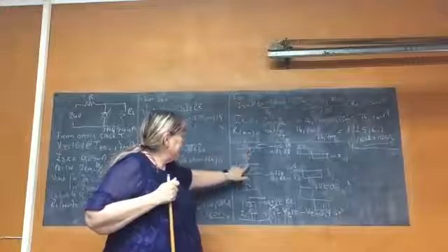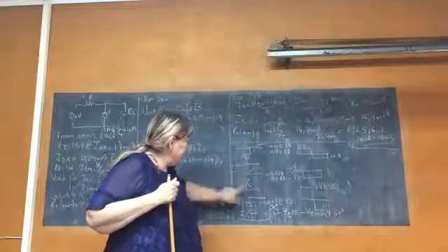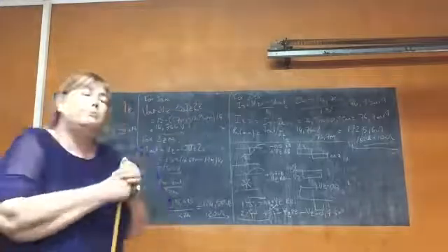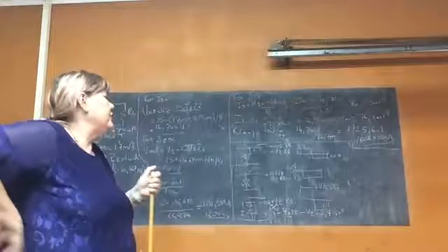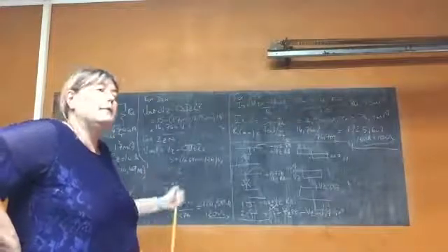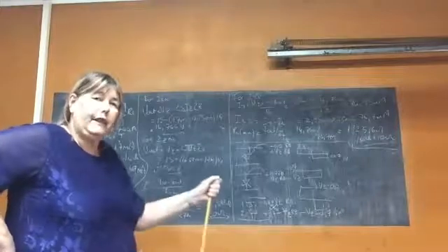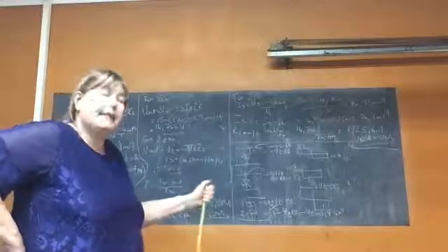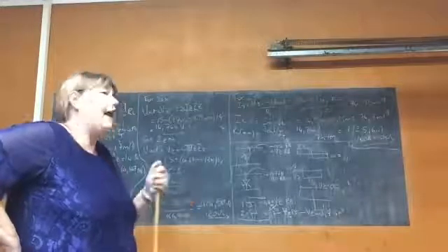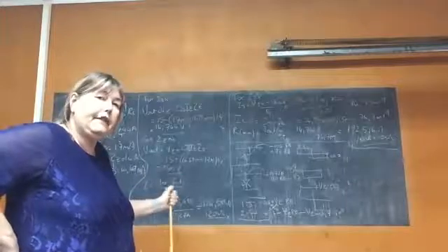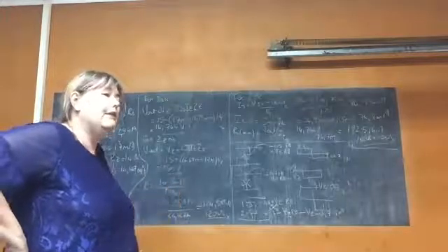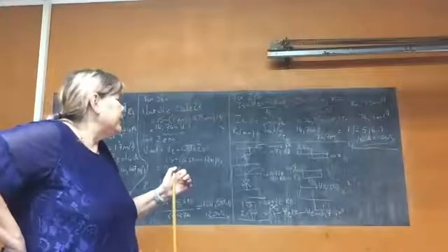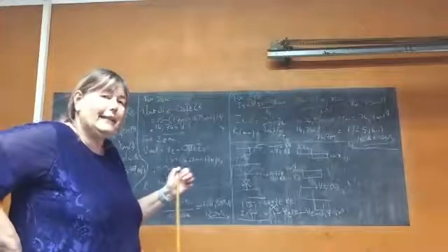Always with reference to this point. Just like with the diode, you pick one point as a reference and you determine what you will get. And if you get 0.7 forward bias negative, you will have plus Vz. If you have plus 0.7 forward bias, you will have negative Vz reverse bias. So that is as easy as it is.